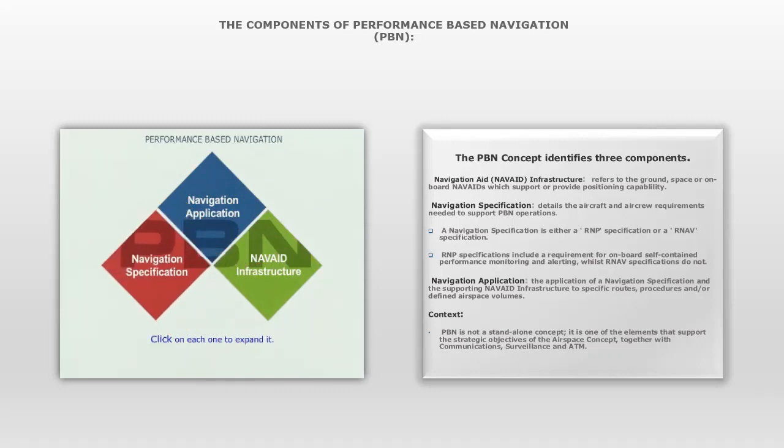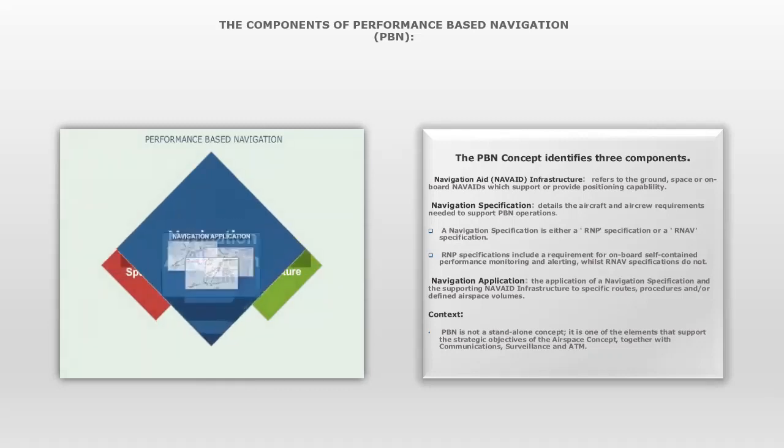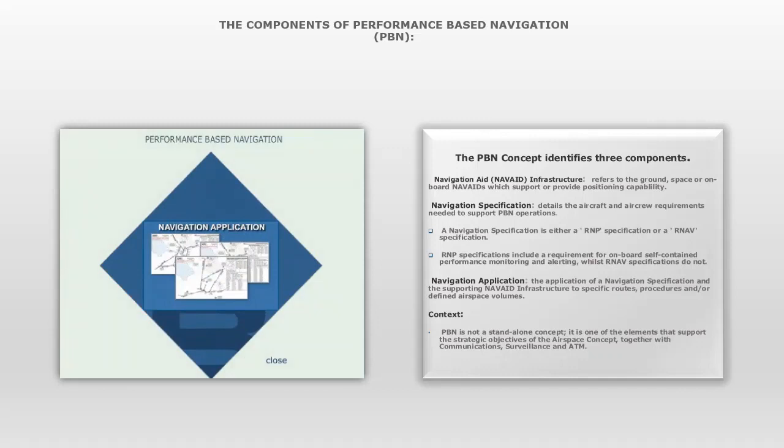Navigation application: the application of a navigation specification and the supporting nav aid infrastructure to specific routes, procedures and/or defined airspace volumes. Context: PBN is not a standalone concept, it is one of the elements that support the strategic objectives of the airspace concept, together with communications, surveillance and ATM.